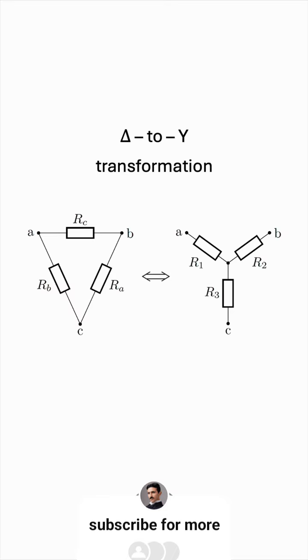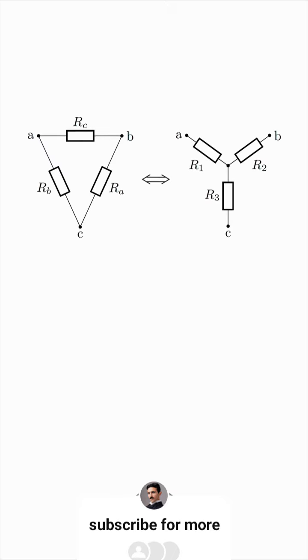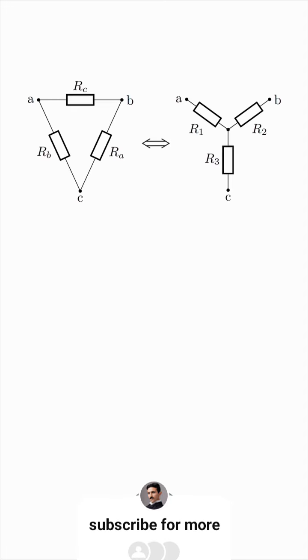But we cannot transform the delta into the Y simply by changing the shape of the interconnections. Saying that the delta connected circuit is equivalent to the Y connected circuit means that the delta configuration can be replaced with a Y configuration without changing the terminal behavior. Meaning, for the two interconnections to be electrically equivalent, the resistance between corresponding terminal pairs must be the same.